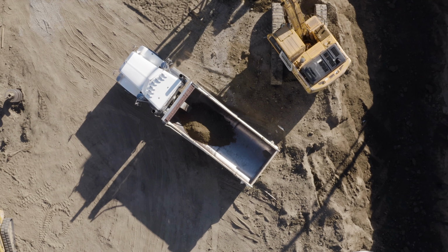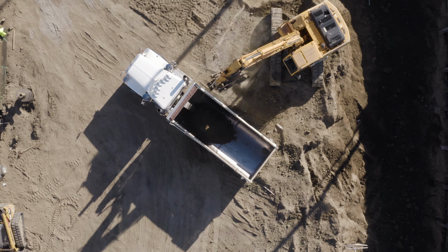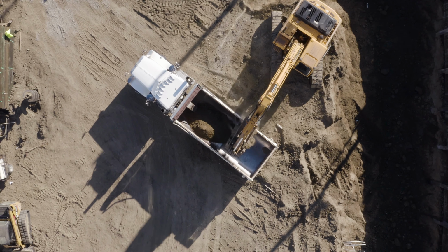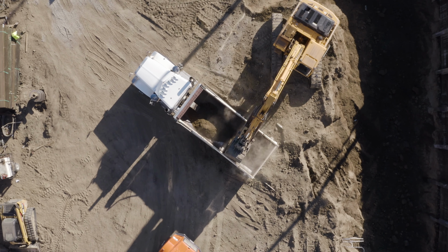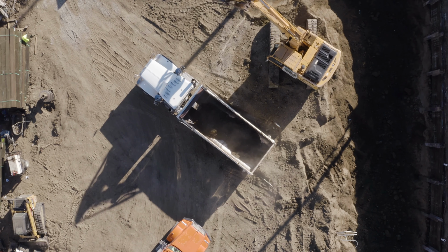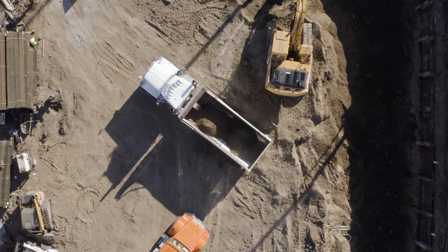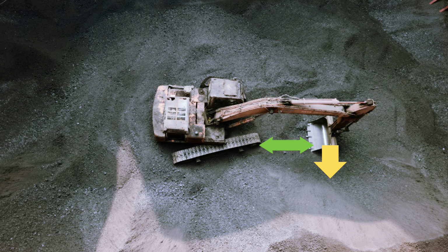Excavator dynamics also includes the detailed study of machine stability, which is critical for safe and efficient operation. During excavation, the excavator frequently lifts soil or rock while the bucket is positioned at a large horizontal reach from the machine's center of rotation. This creates a tipping moment around the edge of the undercarriage or the track contact line with the ground. The magnitude of this tipping moment depends primarily on the weight of the lifted material and the horizontal distance between the bucket load and the tipping axis.